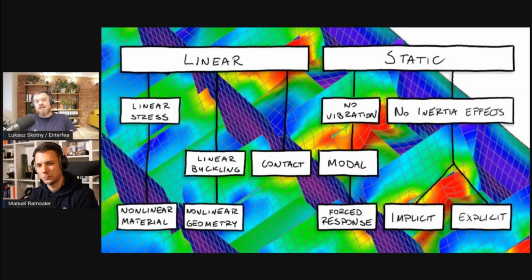Of course, one can argue, okay, but maybe the 76th modal pattern only includes a handrail on a 7th floor somewhere near the stairs. So if that breaks, then you think, okay, not a big problem, let's build the thing, and then we'll just dampen this particular handrail. The problem with modal analysis or even forced response analysis, as far as I understand it, and I talked with people who do it, is that it's extremely difficult to make a model that represents your structure dynamically well enough to believe in the outcomes you receive.